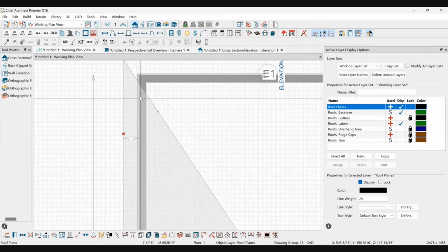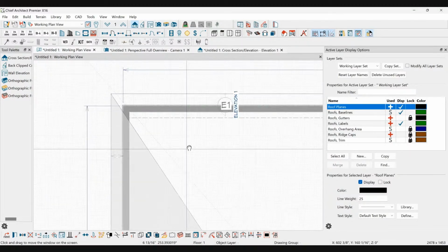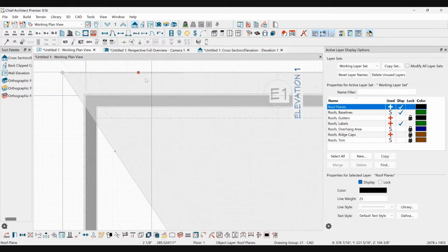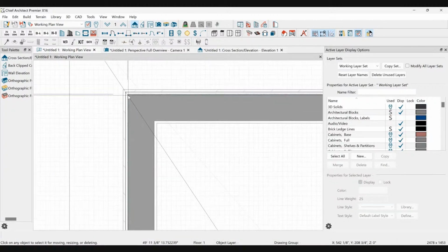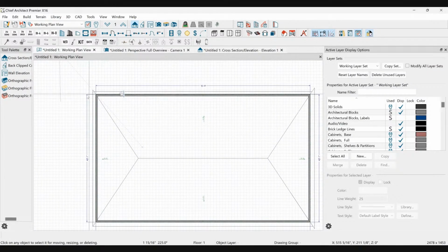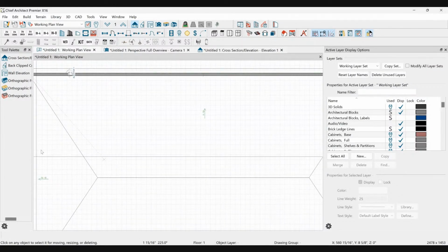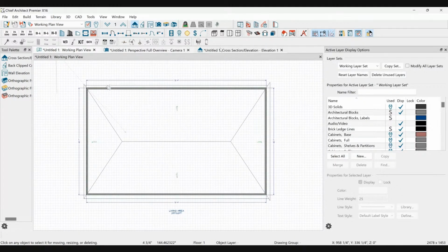And so what you're doing is you're basing it on a particular height and geometric location in XY on the plan. In this case, this roof plane used to be in a normal spot, but then we moved it in the Z direction down 4 inches and we got this problem. Now, if I bring it back up 4 inches and then rejoin the planes, it brings this right out to the corner and everybody's happy. So of course, if you change your pitches back, it would be 45 and all that stuff. So yeah, that's our little bit of a lesson today.